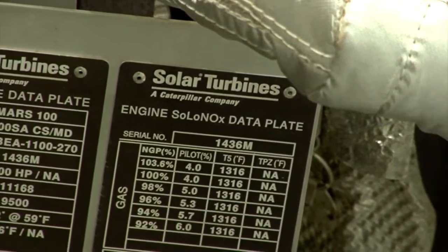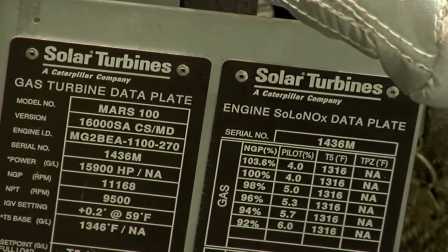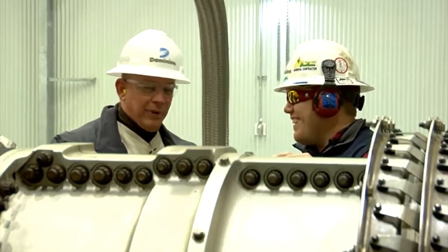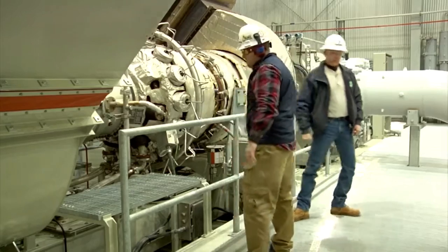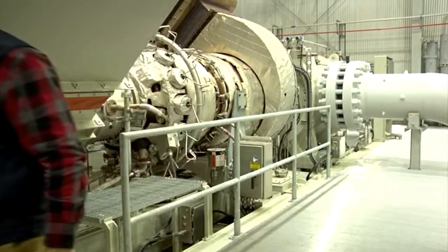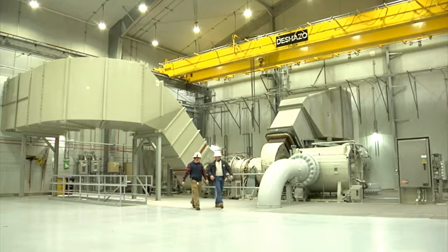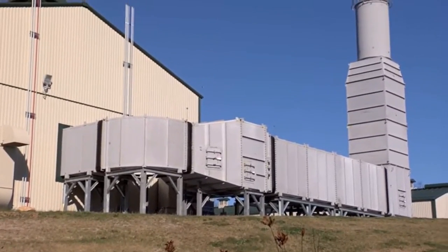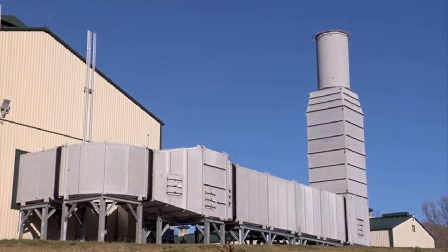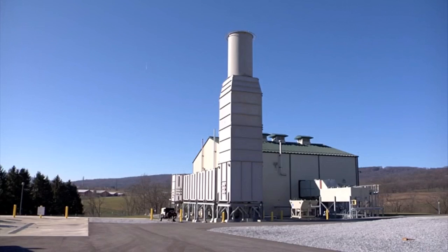We've gone to primarily utilization of solar turbine. Solar turbines, from our standpoint, are state-of-the-art equipment. They have what they call a low emissions package that Dominion buys from them. It's a gas-fired turbine engine that drives the compressor. And by process of burning the natural gas to create the power to turn the compressor, the actual exhaust goes through an oxidation catalyst, which further reduces the emissions. To the fact if you're standing at a natural gas compressor station and you're looking at the exhaust, you see no emissions. There are no emissions visible at a natural gas compressor station.